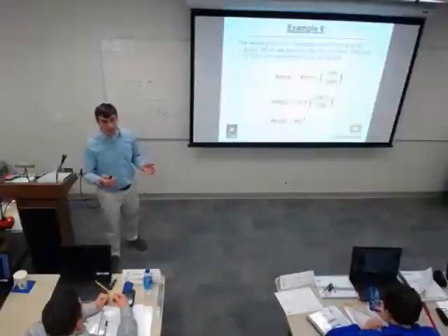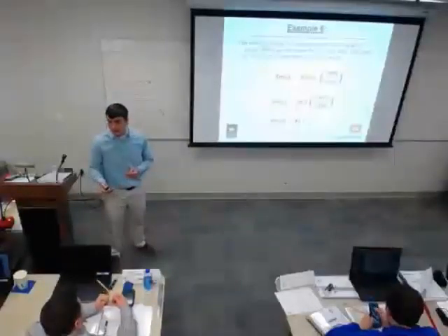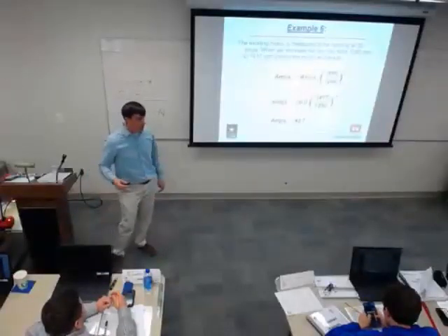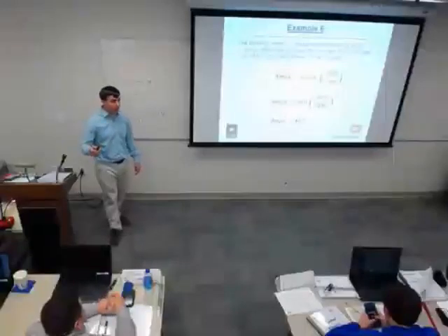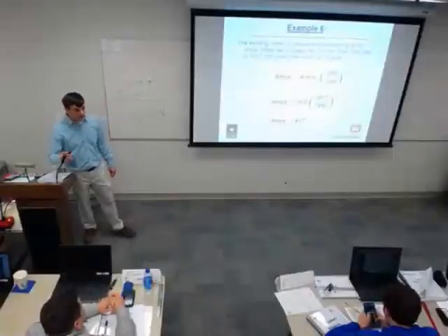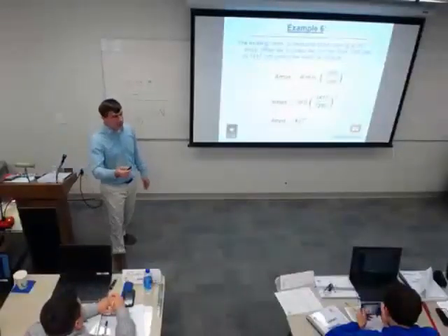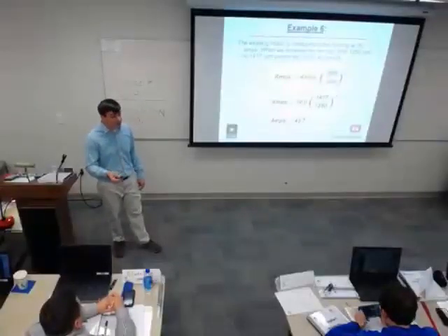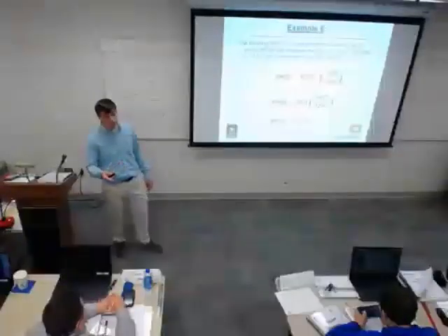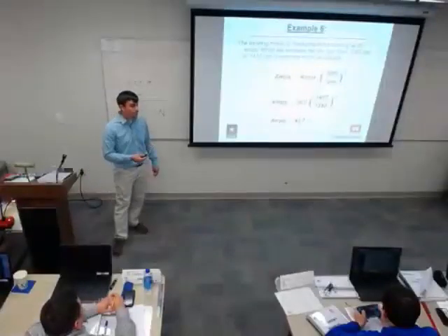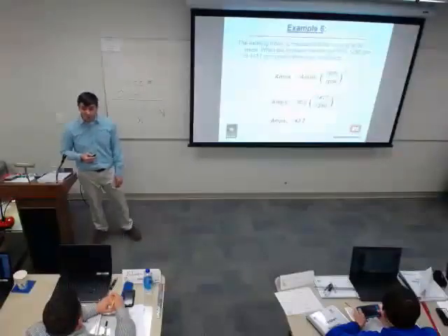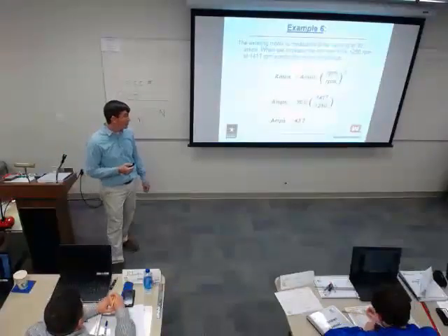So what sounded like not that big of a deal RPM-wise, would this change matter? Oh, yeah. Very likely. What all could that impact? Overloads, wire size. Everything. Breaker size, conductor sizes, disconnect size, everything could potentially change. Motor size could potentially change because of that. So that's where you got to be careful. Going up in airflow rate can be dangerous.